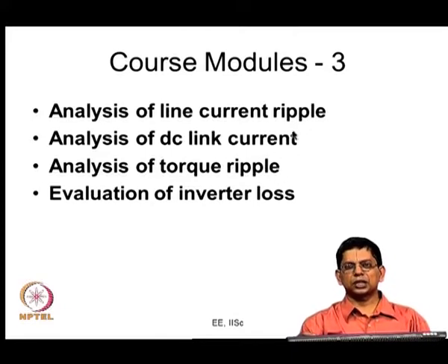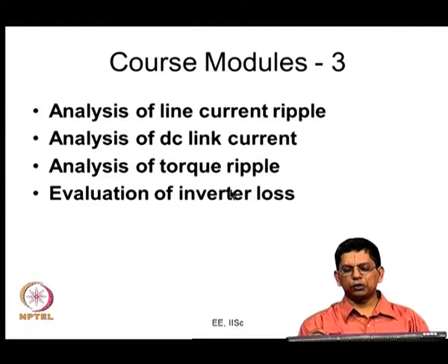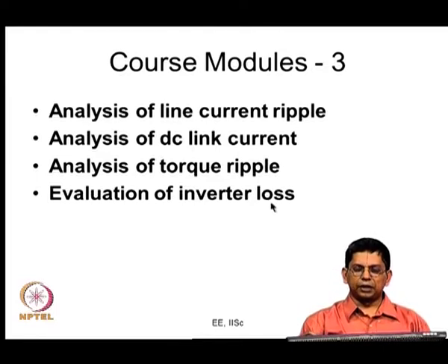So, the basic principles are essentially the same. The inverter losses are a little different here because you may have 2 devices conducting concurrently, and your switching loss would involve VDC by 2, but the same ideas are still valid. For the switching loss, you need to come up with E on and E off of the devices, and then you can certainly calculate them.